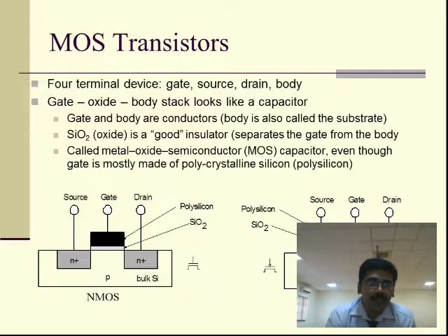And there is one more region called the saturation region. In order to form the saturation region, the same condition must be met as in the linear region. We make VGS greater than VT, and as far as the saturation region is concerned, the channel is not going to be uniform, instead it will be a tilted channel.